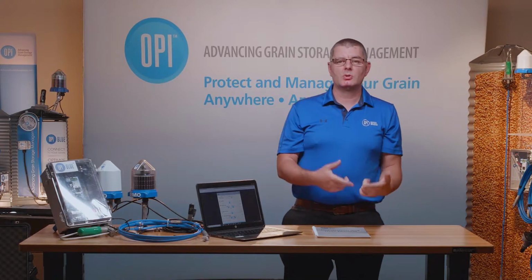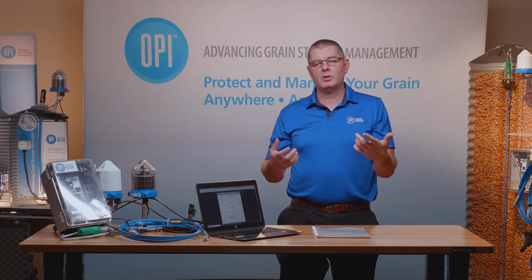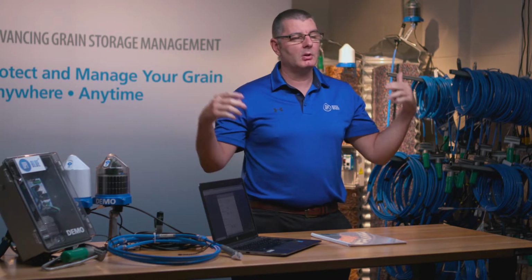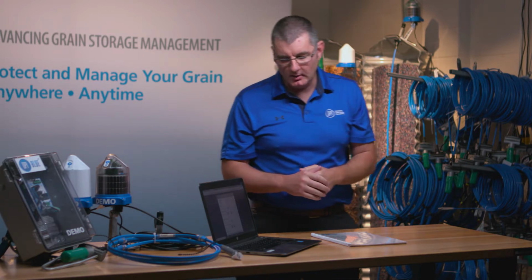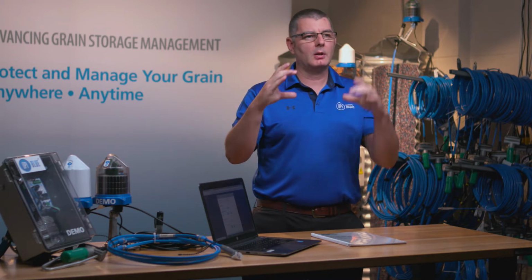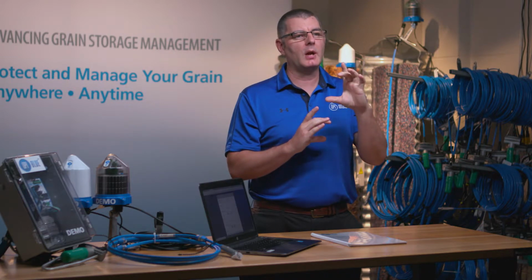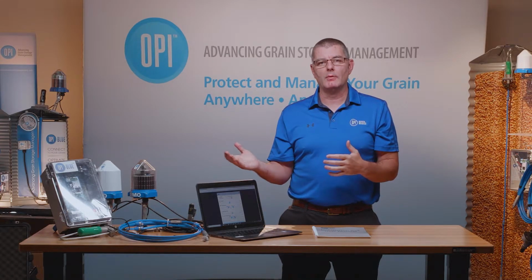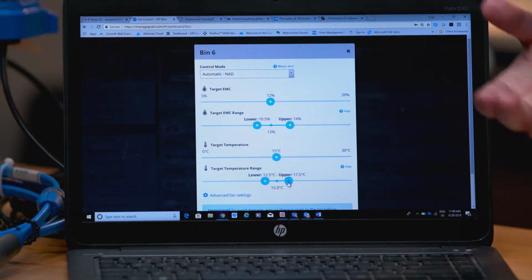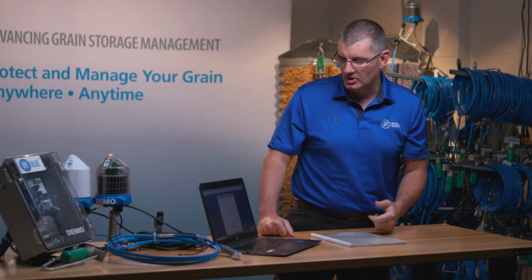Once you've got that set, you just go ahead and save the changes that you've made. And then, like I said, the system with the algorithms that are in place is smart enough to know if the conditions are met with ambient conditions, it's conducive to run the fans. And the same thing when the fans are running, if the conditions fall outside those operating EMC and temperature target windows that you've created, the fans will shut off. So it's a great way to not have to think about and manually stop and start your fan and efficiently drive towards your targets, which are going to save you a lot of energy as well.